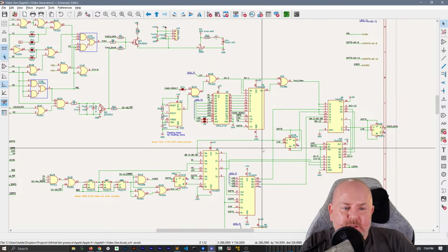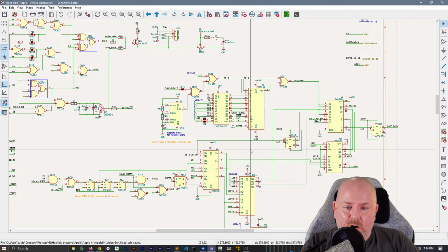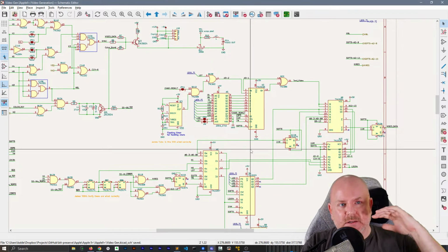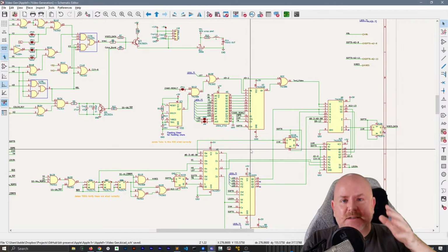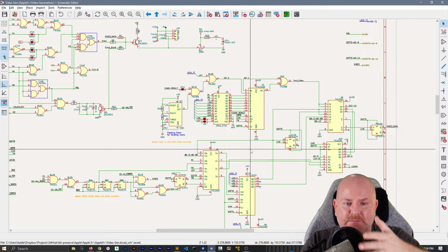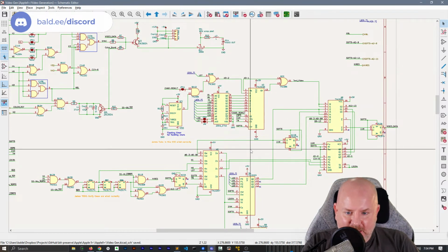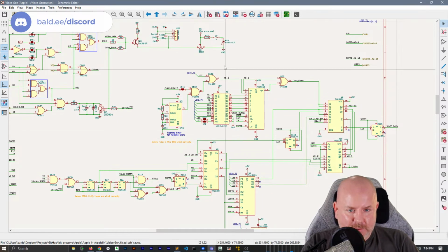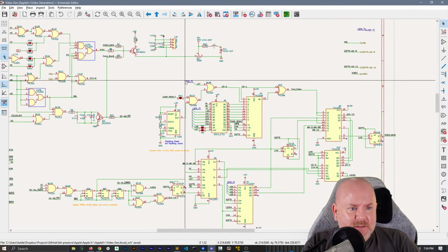What was really cool was you could set up a Macintosh or a Power Mac to be a FireWire hard drive. If you're having trouble getting it to boot, the chipset supported a target mode. Let's say your RAM was hosed, you could get the computer's hard drive to show up as a FireWire drive, so you could copy files off of it as a last resort, or as a backup, or whatever. It was a really cool mode. I actually kind of missed that.